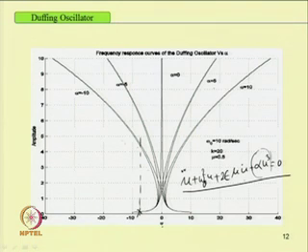Due to the presence of these multiple solutions, we should know what the system response will be at that frequency. It depends on the initial conditions we have taken. Depending on the initial conditions, it will have either this value or this value or this value, and whether these responses are stable or unstable, one should study. Then, depending on the stable or unstable solution, one can tell in which state the system response will be. To study the stability of the system, we can take these points as the equilibrium points and perturb about these points to know whether the system response is growing or whether the response becomes bounded.